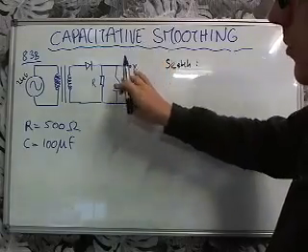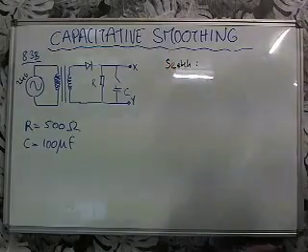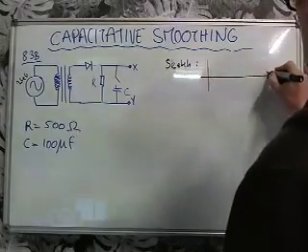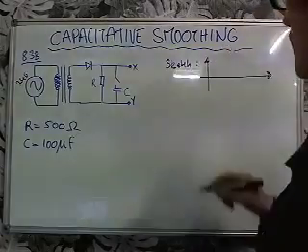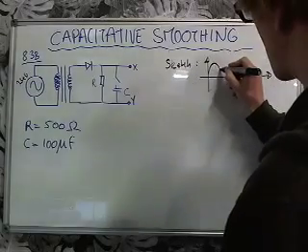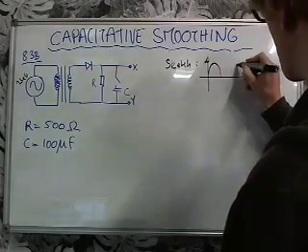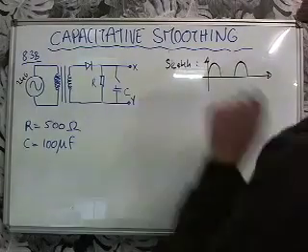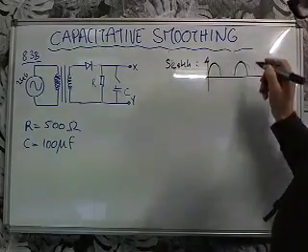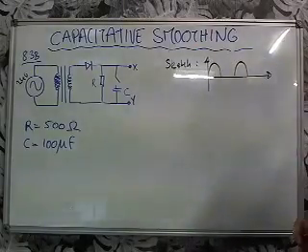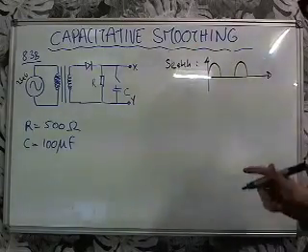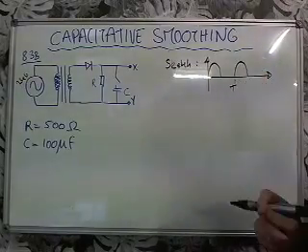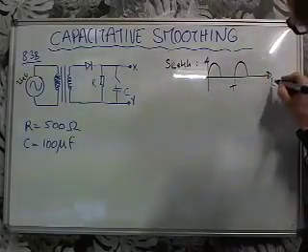And just from our understanding of how half-wave rectifiers work, we should be able to sketch that it's going to be something like this, okay? Where we'll end up with just the positive peaks. There's no smoothing yet, the capacitor's not connected, so we won't smooth these peaks off, it's just the individual peaks, okay? A little bit more information that we could put on there perhaps would be the period T of that. This is time on this axis and this being voltage on this axis, Vxy.